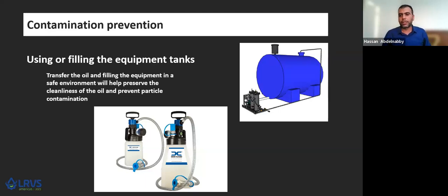That's why you can use different types of canisters that are available from different vendors. I just use a photo in this case, but you can use these to put the oil inside your tank and make sure that you are preventing contamination of this oil and preserving the cleanness level that you struggled for and spent money on your oil.